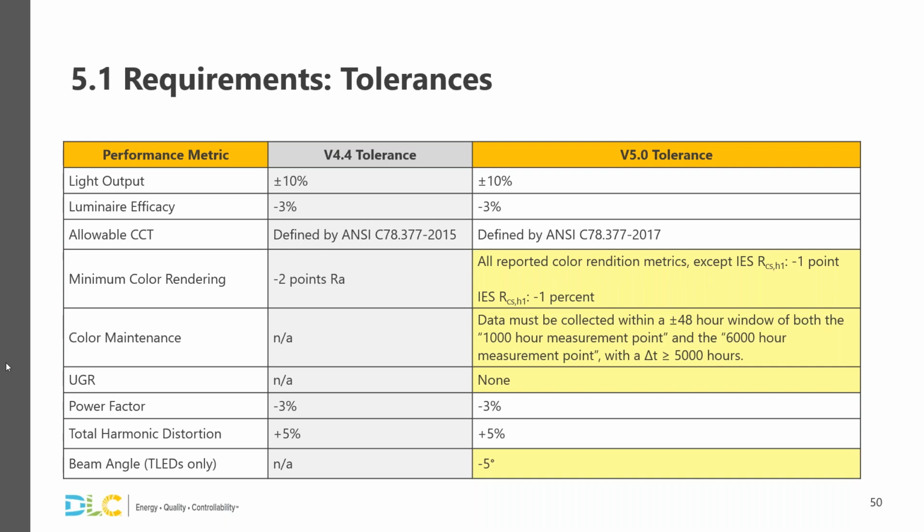So in the draft, the UGR criterion values that were given, for example, for high bays was 25 with a tolerance of 1. So again, remembering that within each step change, each UGR value, you have essentially 3 points within a step. So for high bays, the acceptable range is less than 28. That means that for high bays, you could have a value that is between 25 and 27.9, and that is in the same UGR step.